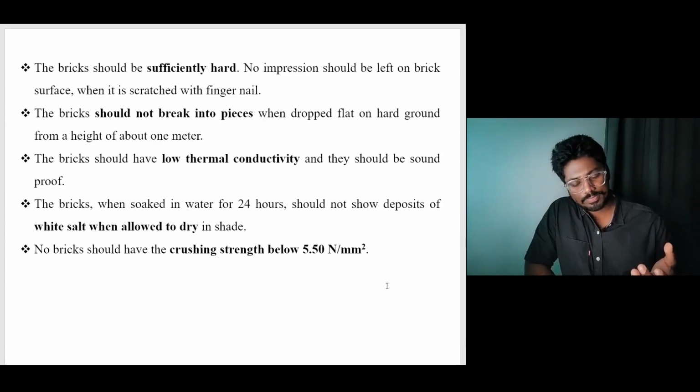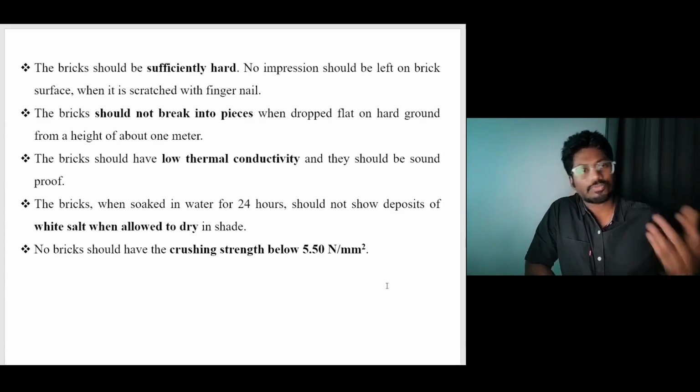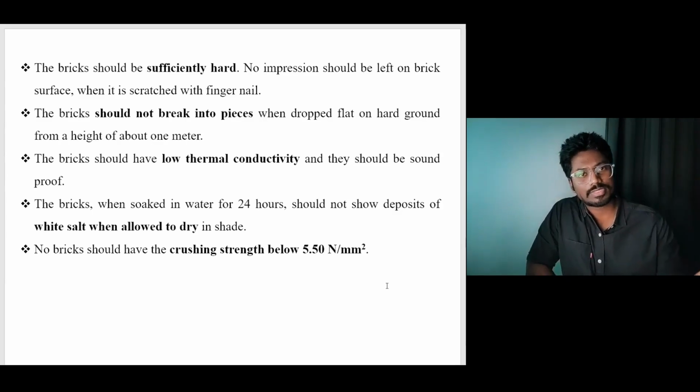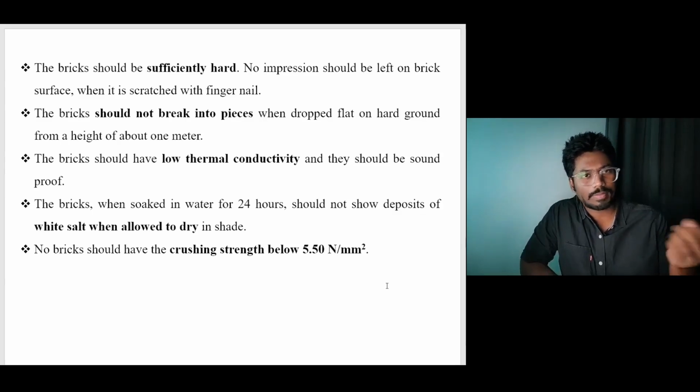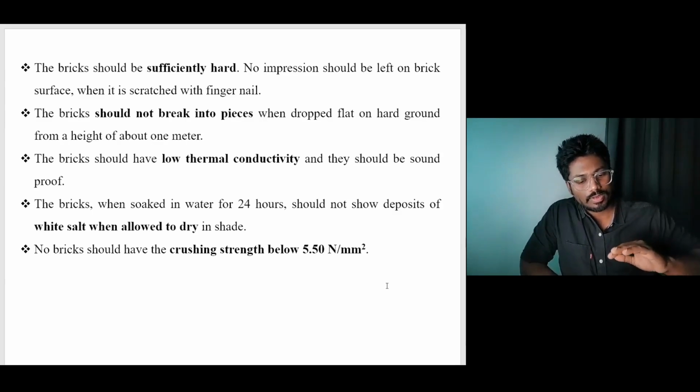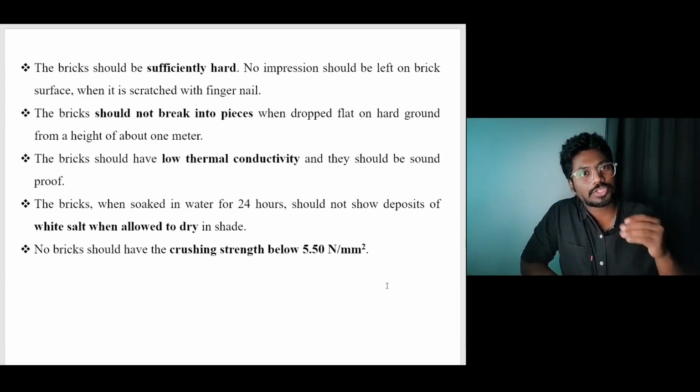Hardness is about, for instance, to examine this on site, if you're taking a brick and trying to scratch it with something slightly hard, maybe a fingernail or a nail, the brick should be able to withstand that scratch. I mean, it should not be exhibiting any sort of marks of that particular scratch. Only then you can say that the brick is actually hard.